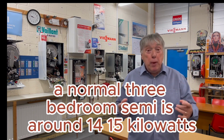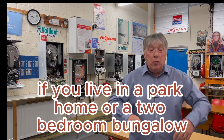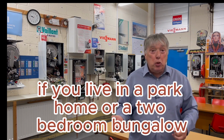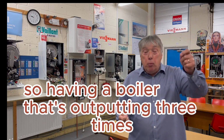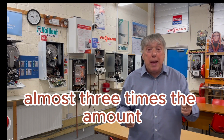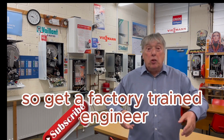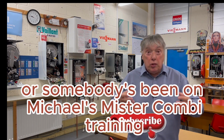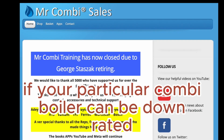A normal 3-bedroom semi is around 15 kilowatts. If you live in a park home or a 2-bedroom bungalow, you might be nearer 9. So having a boiler that's outputting 3 times, almost 3 times the amount, is a complete waste of gas, and you're paying for that. So get a factory trained engineer or somebody who's been on my course, Mr. Combi Training, get them to have a look if your particular Combi boiler can be downrated on the heating side.